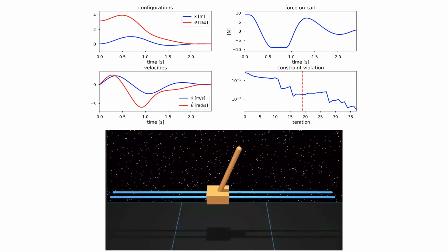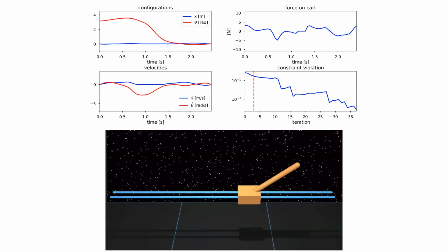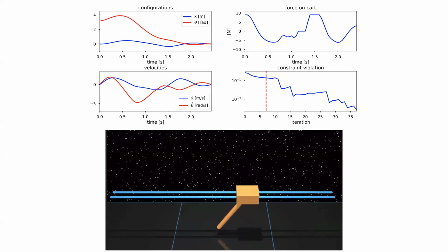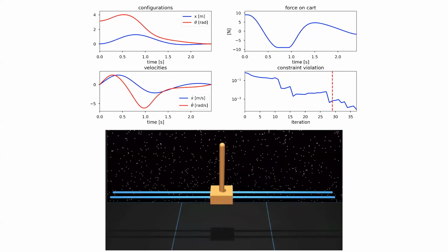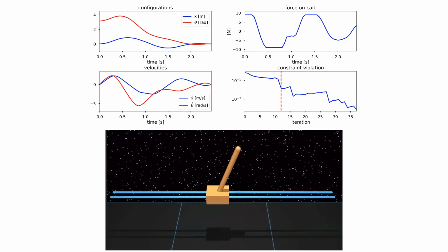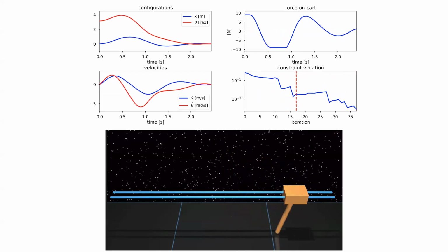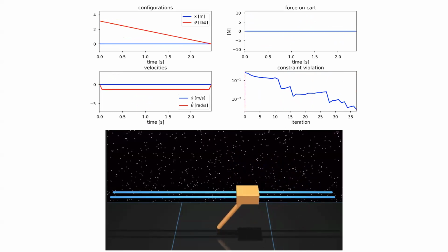So here is everyone's favorite trajectory optimization example to get things working. Here's a cart pole swing up. Start with the pole down, and we constrain it to be at the top at the very end. And this is a cool problem because it's relatively nonlinear, so it tests how well your approximation method works. And then on the top, we see how the actual iterates of the solver itself converge on the solution.